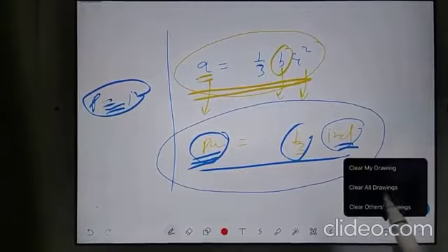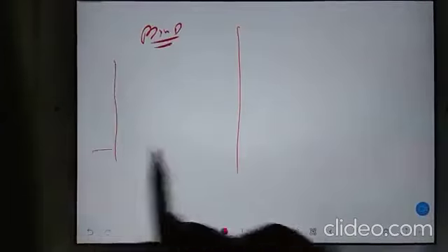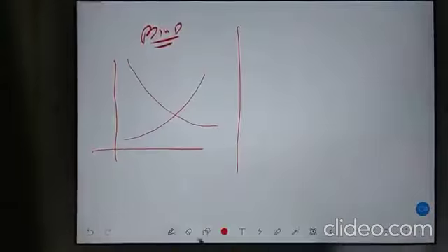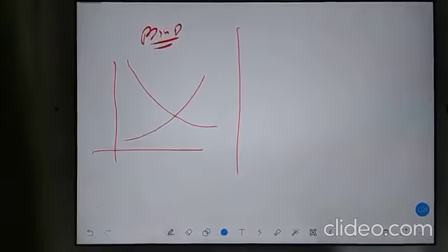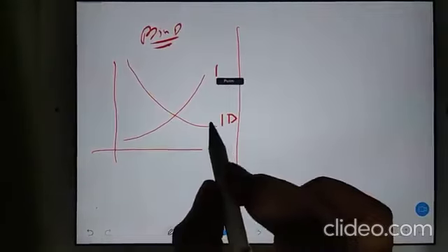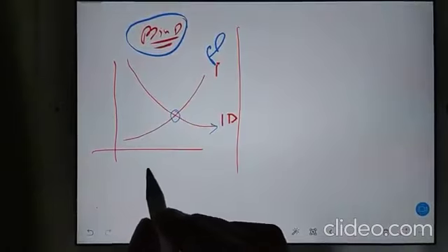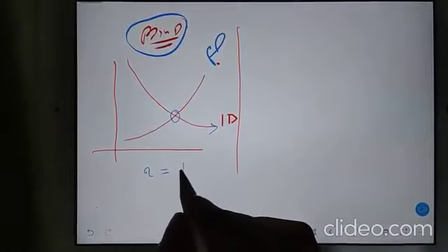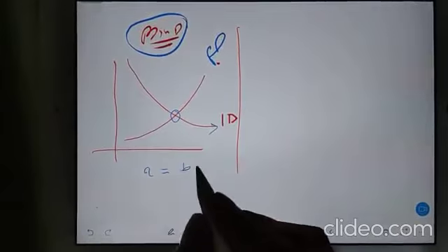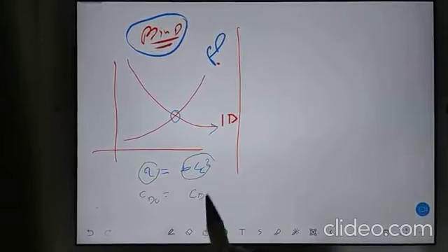First, I will summarize again. See guys, in case of the minimum drag condition, in this graph, you got one line like this and one line like this. Which line was the induced drag line and which was the profile drag or parasite drag? Can anyone tick here? Very good. This was induced drag. So you can see here, in case of minimum drag condition, they both are exactly equal. So you can write A is equal to BCL square, because this entire thing is your CD naught and this entire thing is your CDI.